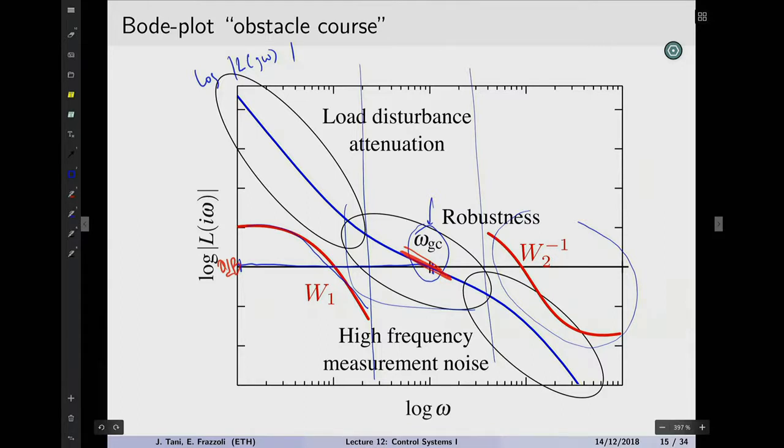That's because it's related to the phase margin of the system. The intuitive way of understanding it is, we saw that we could approximate the closed loop bandwidth with the crossover frequency by assuming a 90 degree margin of phase. So this slope determines the margin of phase. It is related to the phase of the system, and therefore influences the margin of phase.